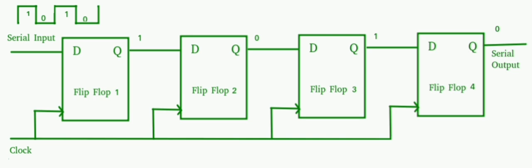Non-binary ripple counter, decade counter or mod 10 counter. In a non-binary ripple counter or decade counter or mod 10 counter, used states equal 10 and unused states equal 6. Output frequency of mod 10 counter equals f by 10.